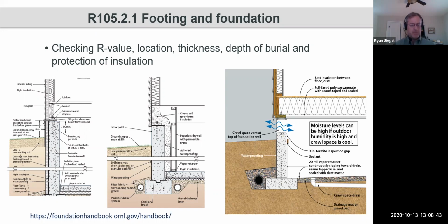But along with this, we also note here the illustration on the right is showing a vented crawl space. So the footing and foundation may have very little in the way of inspections for vented crawl spaces, but noting here, because the flooring insulation and the like for that thermal envelope would be included during subsequent inspections.